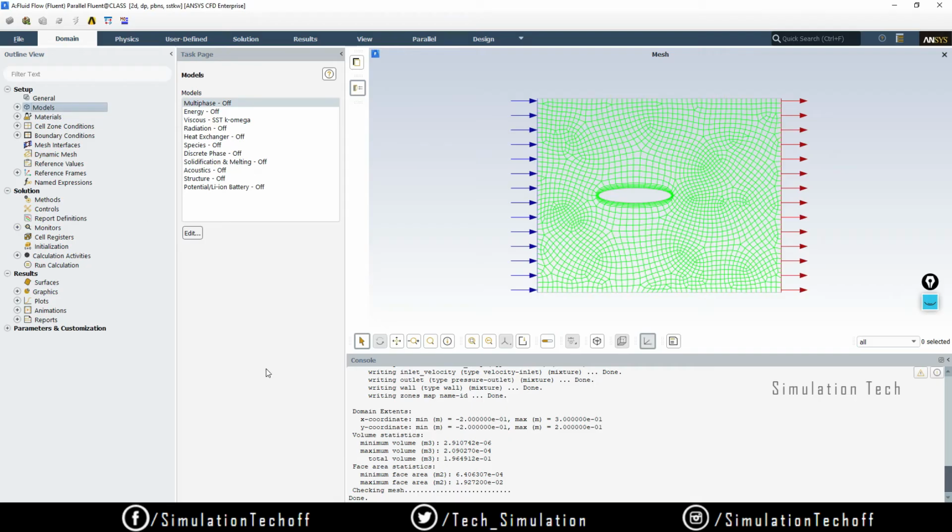So this model is very important, and I hope you heard about this term. We already discussed these things in the introduction of CFD, where we talked about the CFD solvers. The CFD solvers basically solve the conservation of mass equation, the energy equation, the species equation, and so on. So if you enable those equations, the equation size will be much bigger, and if you disable the diffusion factor, the convection factors like that, the equations become much smaller.